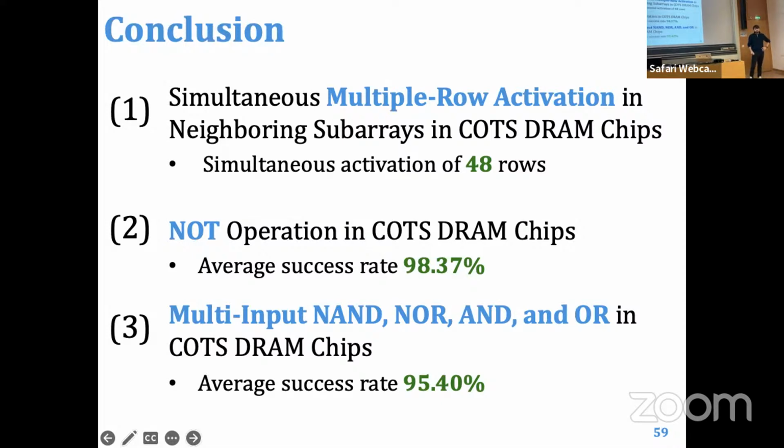Could it be better to do, for instance, if you wanted to do a two-row operation, and you need a 3 VDD by 4 on the reference subarray, could it be better to have 3 rows of VDD and 1 row of 0? Would that possibly give you a more reliable 3 VDD by 4?